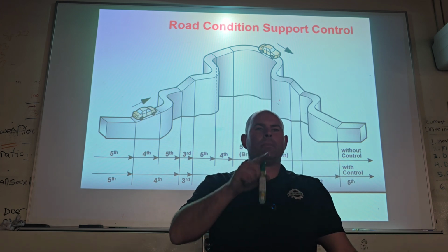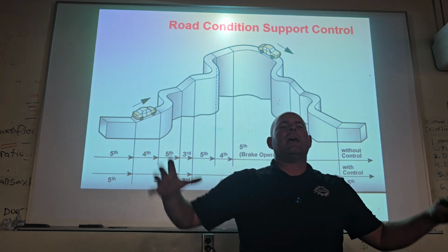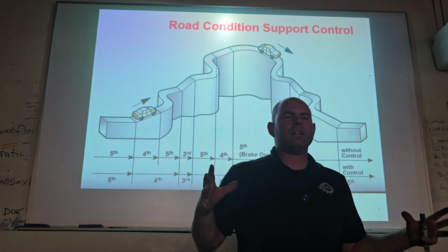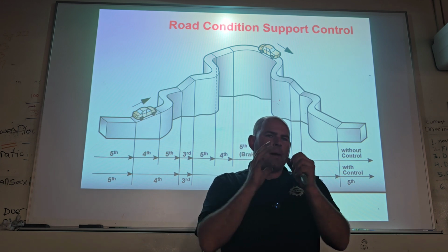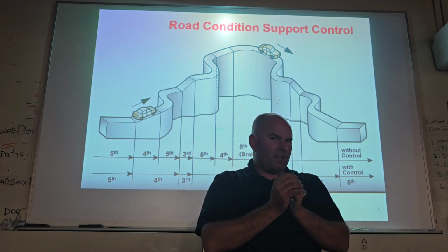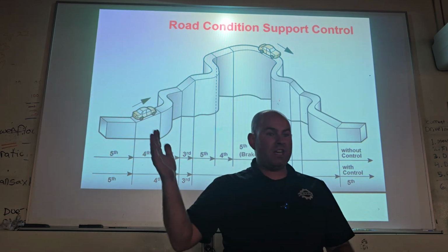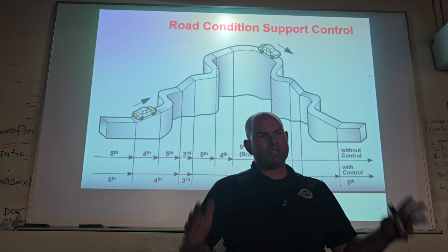It's better for more torque, but remember, every time a transmission shifts, it lets go of a gear and it grabs another gear. So it lets go of, let's say, the ring gear, and then it has to grab a sun gear. Each time that happens, it wears a little bit on the clutch. Can you follow the logic? You don't really want that transmission going third, fourth, fifth, fourth, fifth, fourth, third. It's like, just chill out.